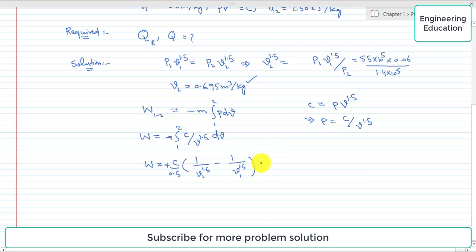So putting the values, we know about these values, and also the value of C can be calculated from P1 V1^1.5. So C is equal to, P1 is 55 bar, so 10^5 converting bar into Pascal, V1 is 0.06 cubic meter per kilogram.